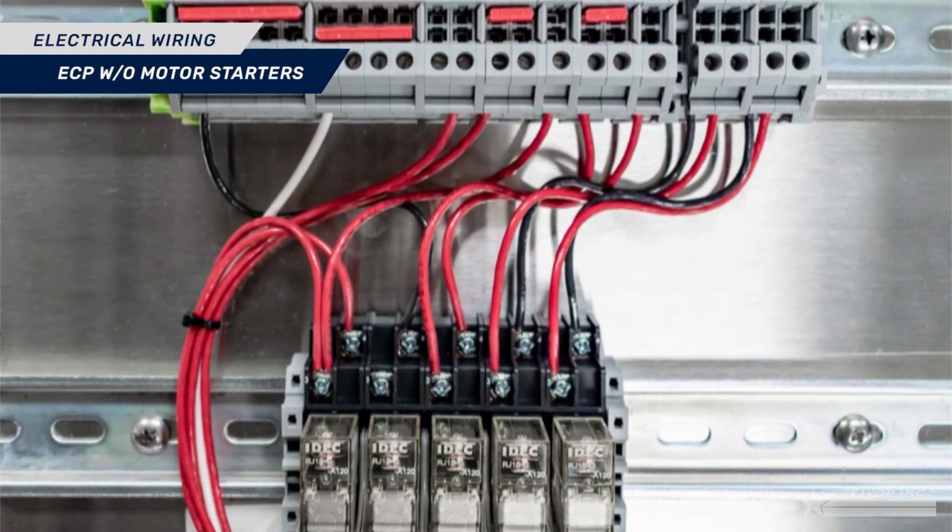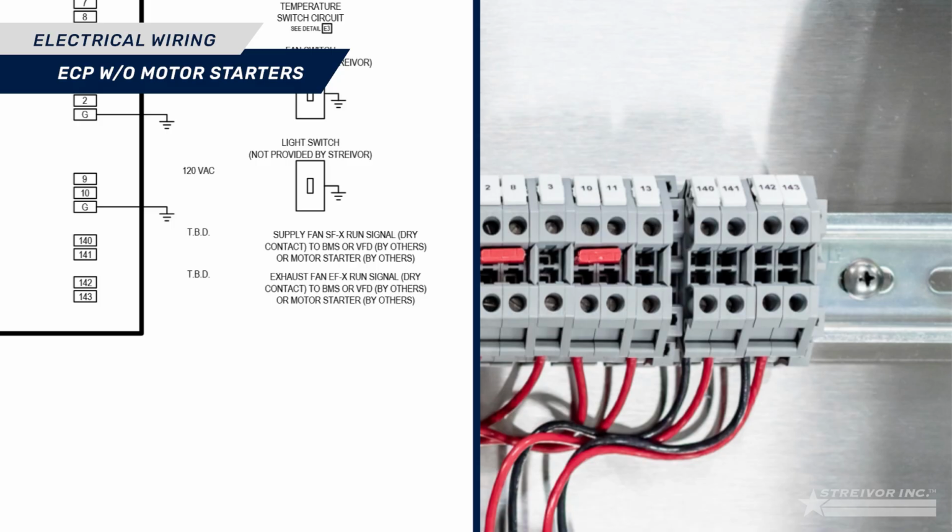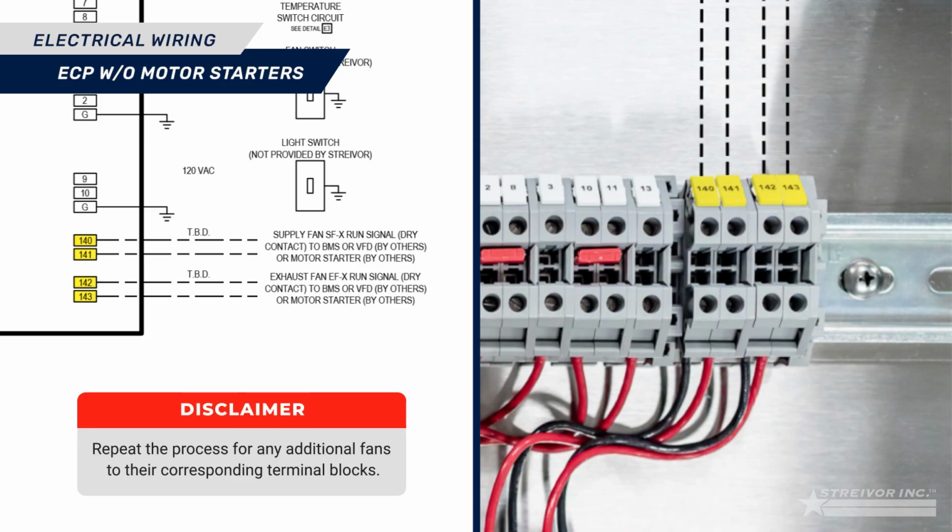For ECPs that don't include motor starters, connect the start-stop fan control signal terminal blocks in the control panel to the designated external destination, such as the motor starters or building management system, BMS.